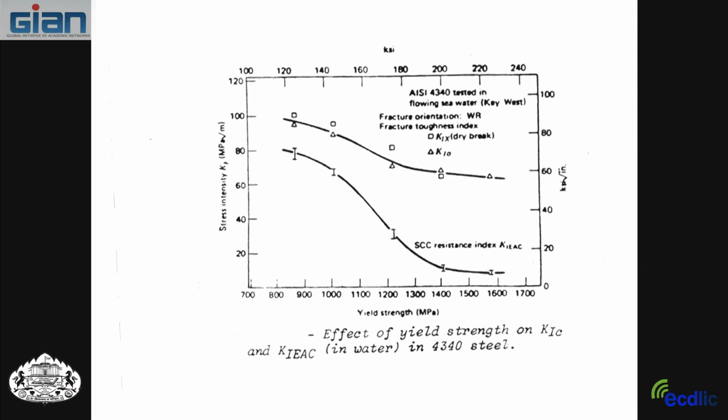And this caused a problem in the initial development of things. People thought that high strength was better because all they knew about was plastic burst, yielding. They didn't want the structure to yield, and so they tried to guard against yielding by making the material very high strength. And then when they made it very high strength, if it got a crack and got into an environment, it had a bad consequence. They grew stress corrosion cracks. And a bad environment could be as simple a thing as rainwater or humid air.